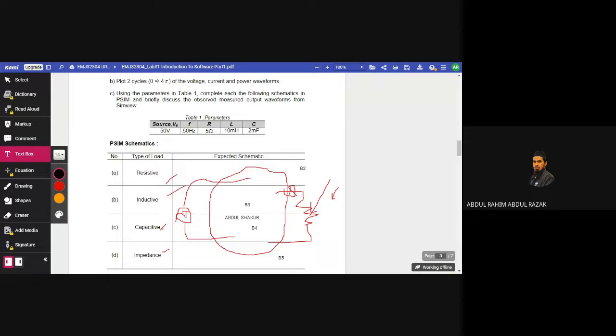Another thing, you can set anything in simulation control, but during scene view, you have to set the X axis, from which hour or which duration up to which duration you want to present. So that is two ways: either you set at simulation control or you set during simulation. Because of that, whichever comes first, it rectifies.